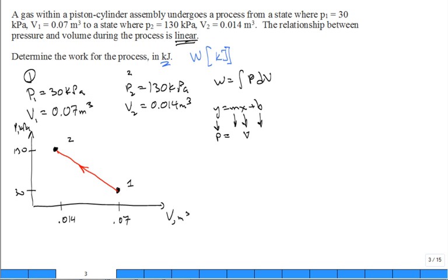So you could do it your own way, but you've got to get it right. But one way I would do it is something like this. I would say, okay, (P minus P1) divided by (P2 minus P1) is equal to (V minus V1) over (V2 minus V1). It's kind of a linear interpolation. And so I can use this equation. I remember that from way back when. And I can stick in any V, and I'll get the correct P. You remember an equation like this? Maybe? Yeah. And so we can then manipulate this equation.